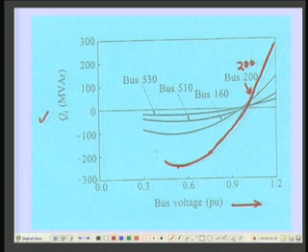It is the minimum reactive power injection required to maintain the voltage at this level. Then to maintain the voltage at any other level beyond this point, again we have to increase the injected reactive power. Therefore, this curve is basically a V-type curve, where when the voltage is very low, you have to inject a certain amount of reactive power. If the desired voltage is more, the required reactive power injection is less.